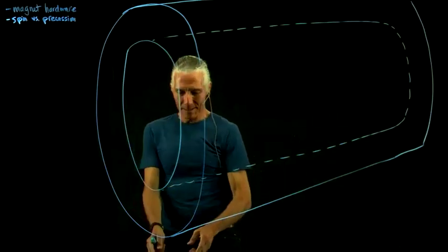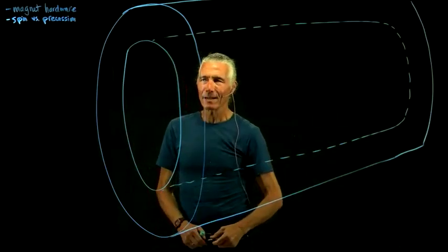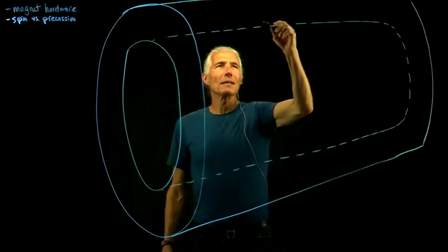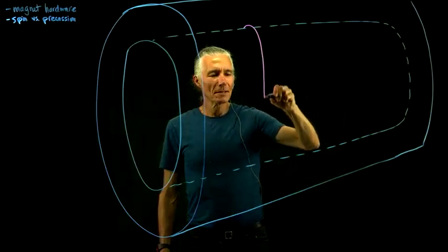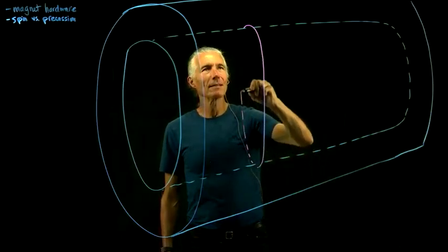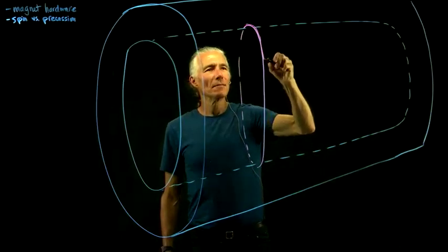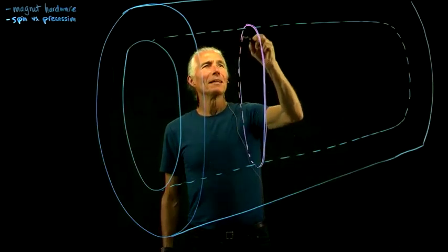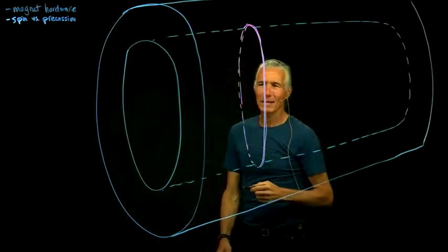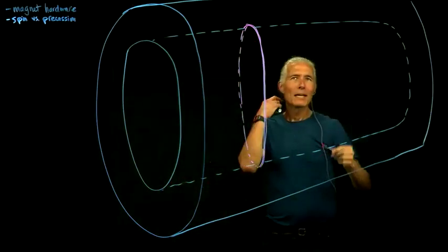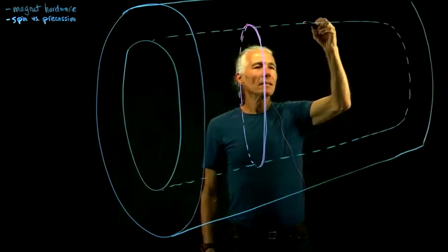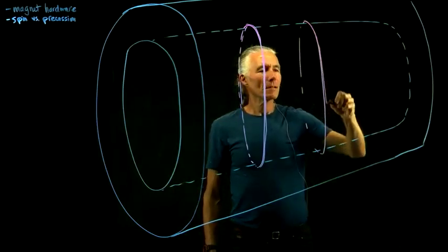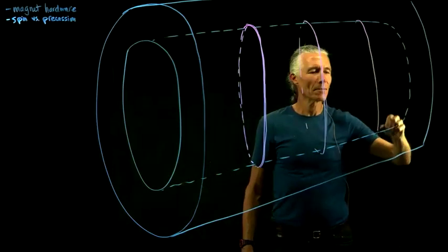And so what causes the main magnetic field? It's these coils that are completely hidden in the magnet. You can't see them. There's a big bundle of titanium niobium alloy, a big bundle of wires, maybe a couple hundred wires, and there's just like 4 of them going around.